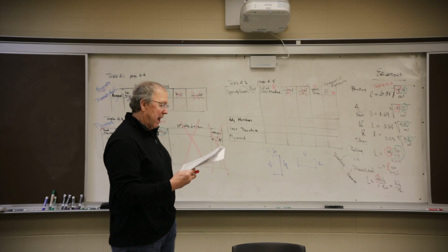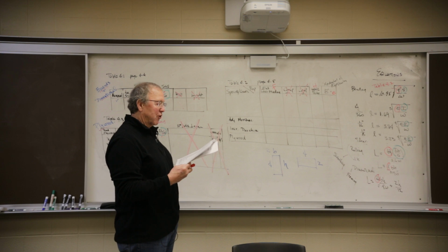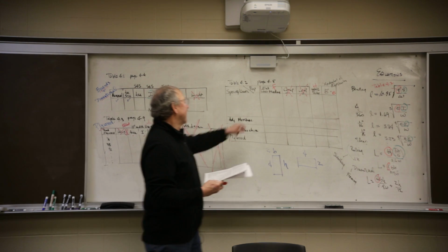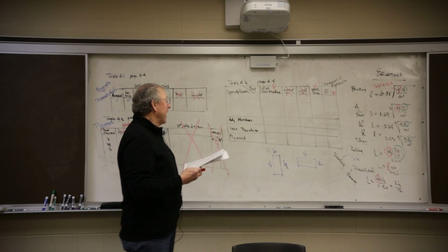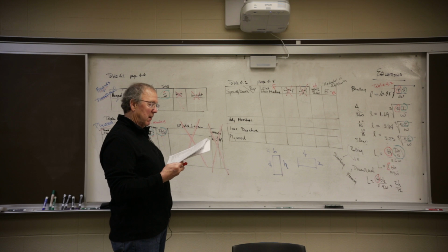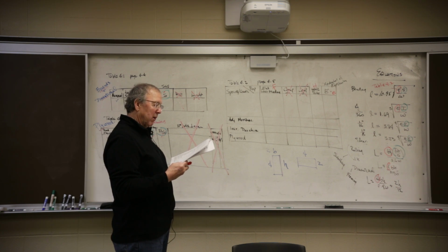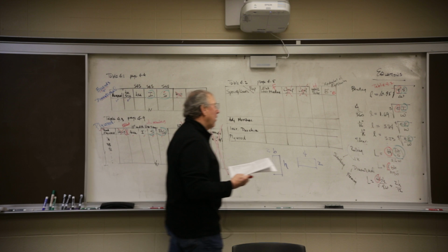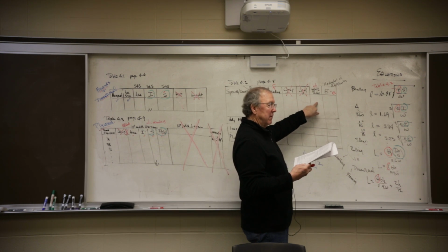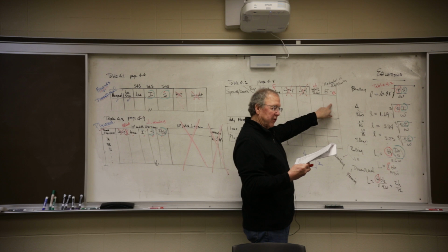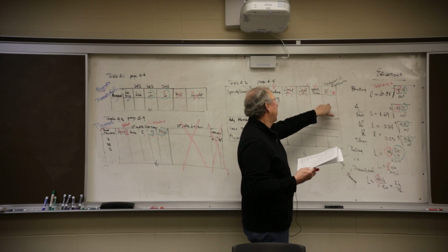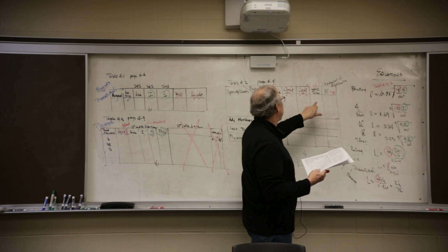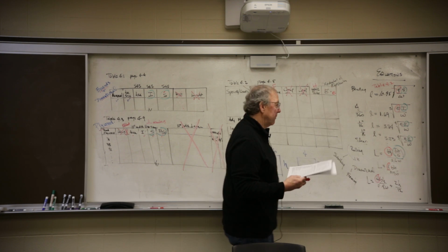Okay, if you look at it, the first column is extreme fiber bending. That's the little f in all those equations. So write that in there. We're not going to be using the next 2 columns. Compression perpendicular to grain and parallel to grain. H in all those columns is this one. And then the modulus of elasticity, E, is the last one. So you're going to need species and grade, bending, horizontal, modulus. This takes care of the bending, this takes care of the shear, this takes care of the deflection.